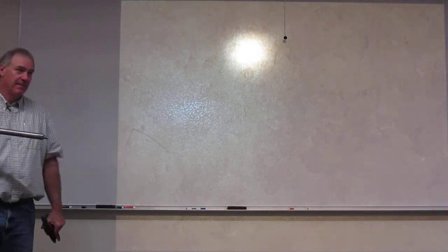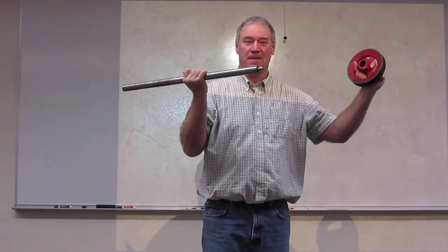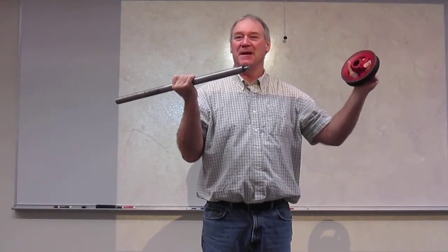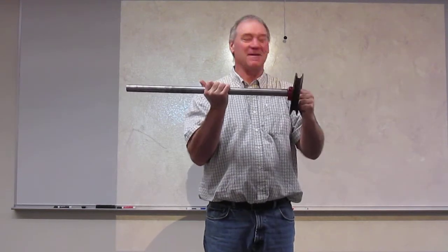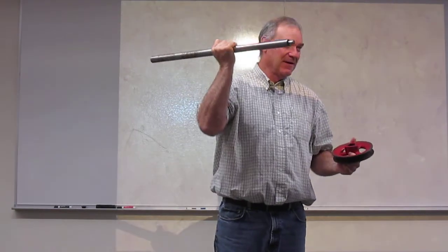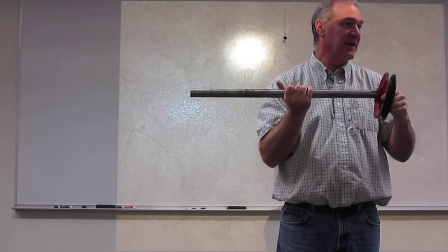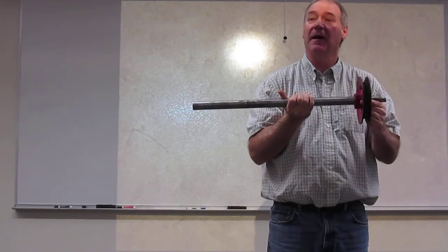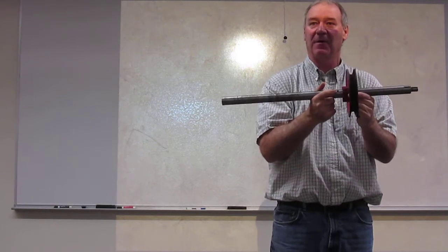Very useful term. Because if I'm trying to join these two parts together, what's the first thing I'm probably looking at? If it fits. Yeah, is how it's going to fit, right? Because if I build this such that it will always fit into here no matter what they're built at, I do not need any hydraulic presses. I don't need anything. I can just hand them to two people and they slide them on and bolt it together.